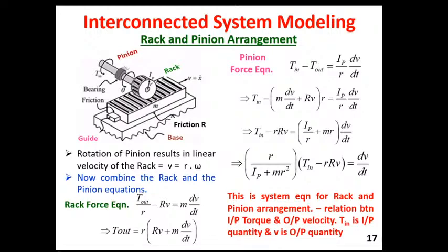Now after transfer function, a very new thing we had done today was the effect of initial conditions on system response, because in yesterday's models every time we had been telling initial condition is equal to 0, but we have seen in the case of the second order system model that initial conditions play a very important role in the system response, because the initial conditions decide what is called the transient part of the overall system response. So if any system is having no initial condition, that means it will have no transient response, so directly the system will try to go to the steady state.